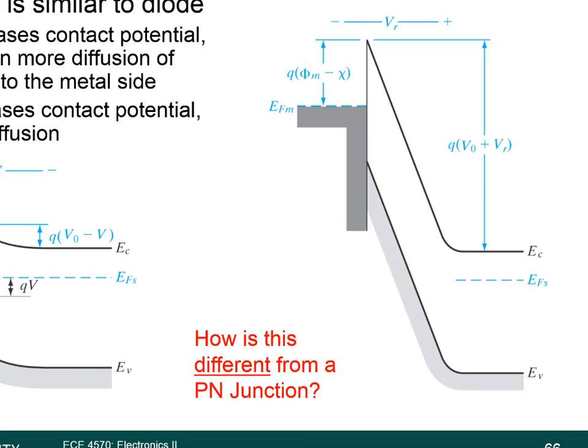Now imagine you're in a lab and you take a metal lead or a metal wire and put it to a semiconductor, and you expect to be able to get current through there. Because of the Schottky barrier, if you reverse bias it, you don't get any current at all. You think your semiconductor device is not working. So that can be a big pain.